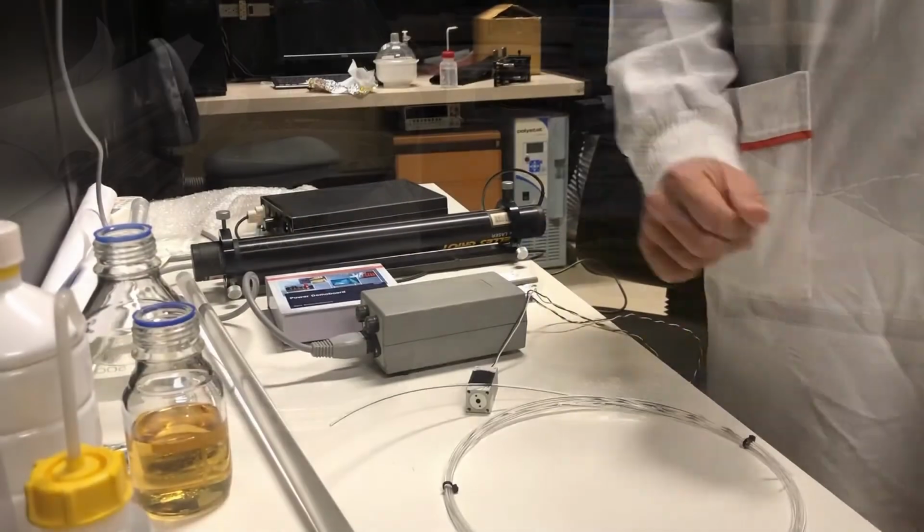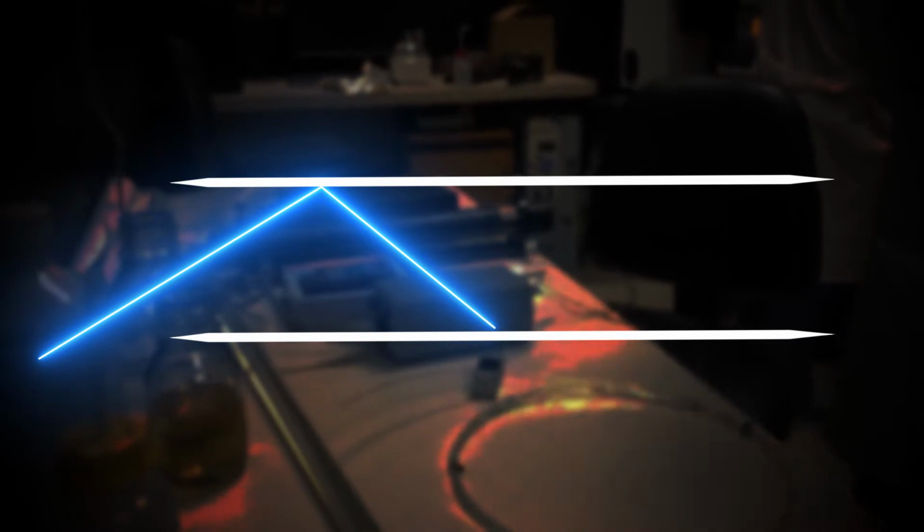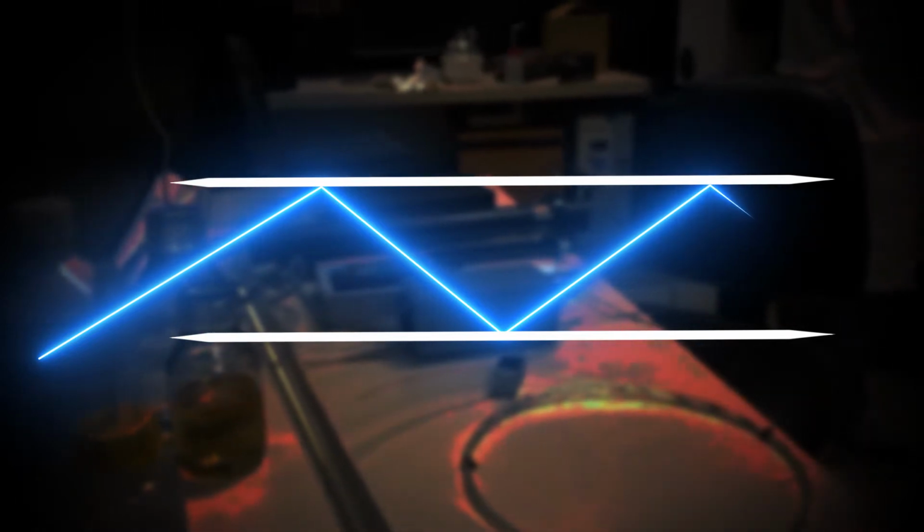The first thing that was seen was the light scattering. This light scattering is related to the alternation of the light's course as it goes through a certain material. It can be called, for simplification, a space light scattering. This can happen due to different reasons, for instance, if there is a defect on the fiber. In this type of scattering, the Rayleigh scattering, it inversely varies with the wavelength. This is a natural effect that always occurs.